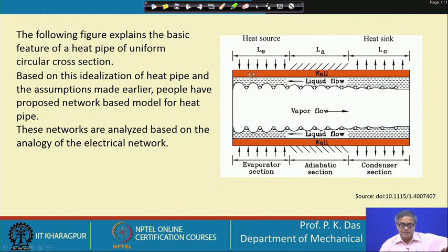You can appreciate, by now we have learnt heat pipe. So, this is the container, which is a tubular container in most of the cases, or wall of the heat pipe, which is metallic and a solid wall. Then very close to the wall, and inside this container, there will be some sort of a wick. There could be different designs of the wick as we have discussed, and this is a liquid impregnated or liquid saturated wick. That means, the pores will be filled up with liquid.